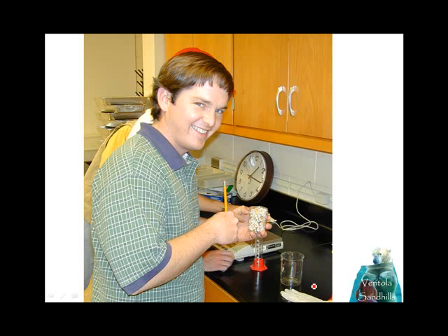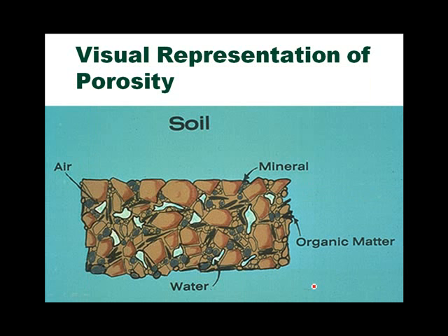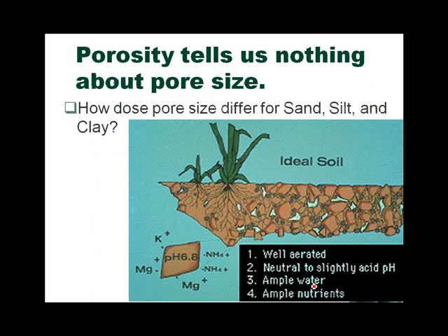Again, knowing the porosity doesn't tell us much about the pore size. And we're going to talk about the ideal representation, this perfect soil, which is 50% solids, 25% water, and 25% air, as we move forward. In reality, we can get pretty close to that.